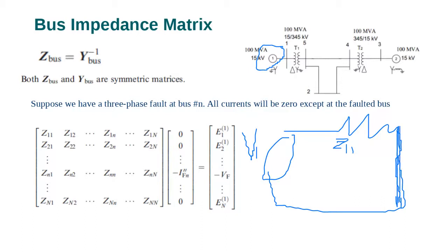Remember, in this course we will give you the fault at the bus, not on the transmission line, not in the middle here. This is another technique that we do in other courses, not in this course. In advanced power system analysis, we do this one. For this course, the scope is at the bus itself. So the Thevenin impedance will simply be this one here, so the fault current is at the bus.